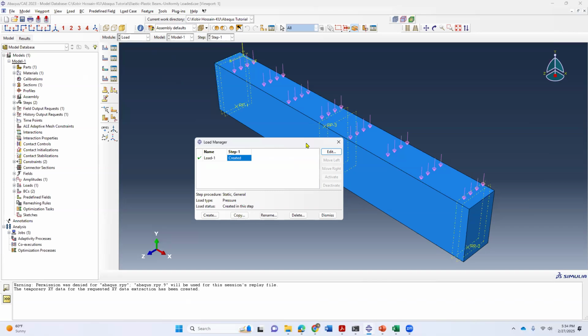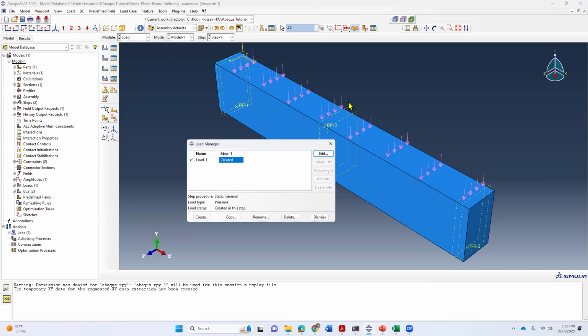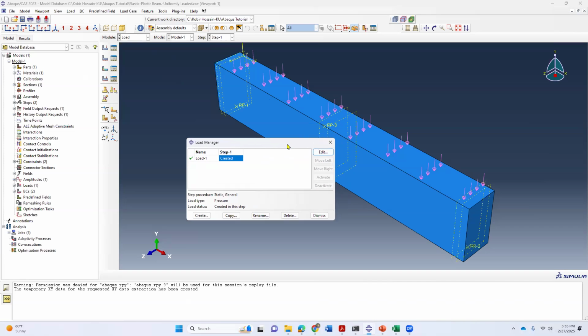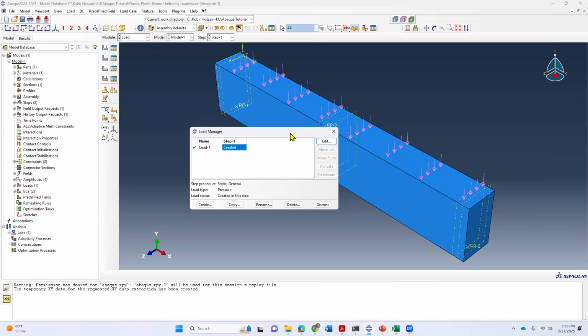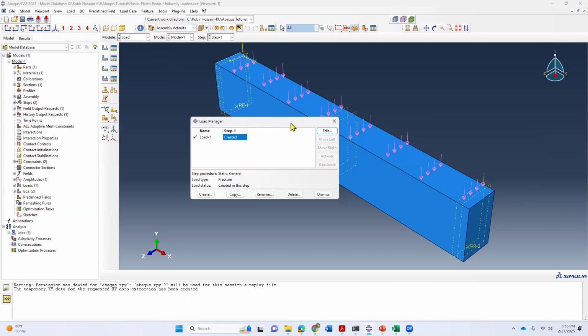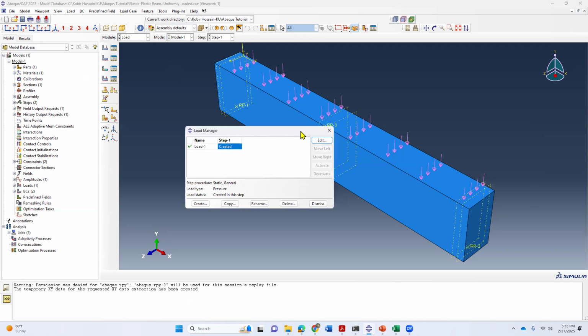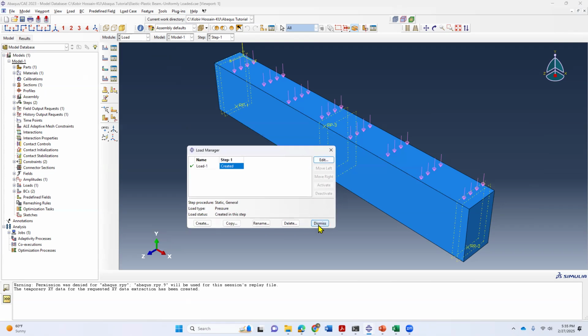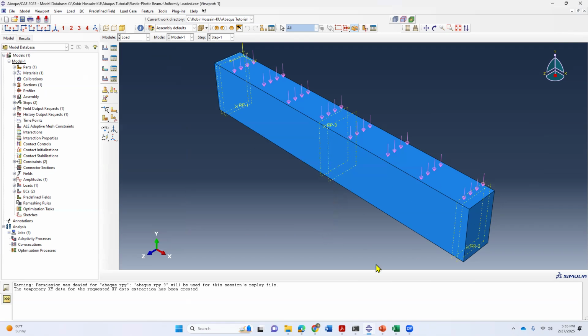So in the lab, when we test a beam, say, we can apply load here or displacement here. Basically, we are applying load, but with a displacement control or a load control method. So we usually apply displacement control load to see at what load it fails. If you just apply a certain load, it will not fail, right? But it's better to see at constant rate of increment of load than the other one.